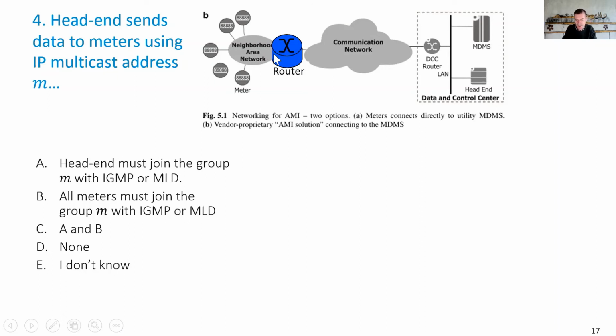Of course, power line communication is limited in quality. It works at home on very short distances at 10, 20 megabits per second. On medium distances in a neighborhood, if you have cables of 1 kilometer or so, you will have extremely small bit rates. So typically you go only to the next hop, that is a router. Then the router, somewhere in the boxes that belong to the utility that runs your network, will go over optical fiber to the communication center of the utility, where you will have computers, for example, a smart meter management system that will gather all the information.